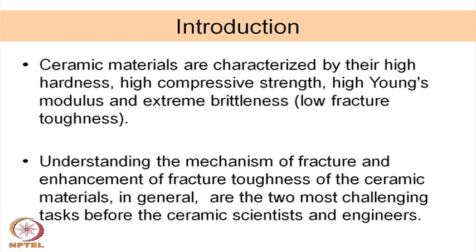Now, understanding the mechanism of fracture and enhancement of fracture toughness of the ceramic materials in general are the two most challenging tasks before the ceramic scientists and engineers, because the material is brittle, it has a high strength, but many a times we are not able to exploit that high strength because of the brittleness or low fracture toughness.